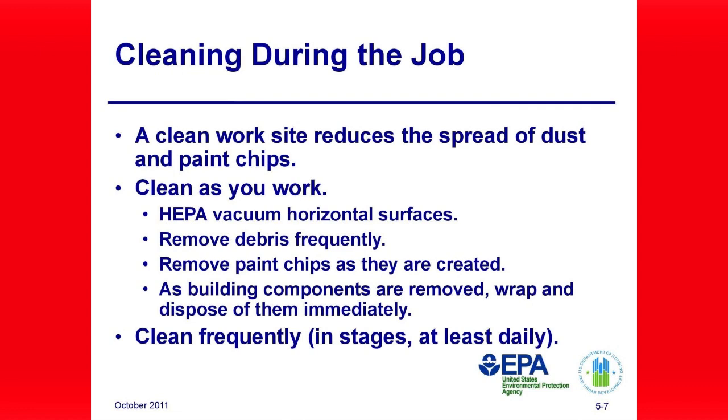All renovation waste from the work area must be contained prior to its removal, storage, and disposal to prevent releases of dust and debris. Chutes for removing waste from the work area must be covered. At the conclusion of the workday, collect waste and store it in containment, in an enclosure or behind a barrier that prevents the release of and access to dust and debris. When transporting waste from the renovation work area, it must be contained to prevent the release of dust and debris.